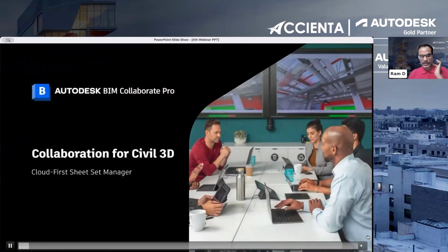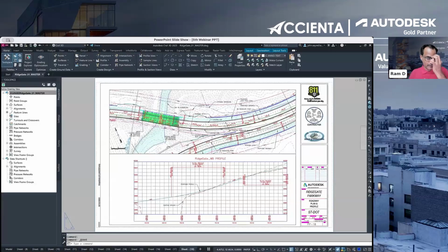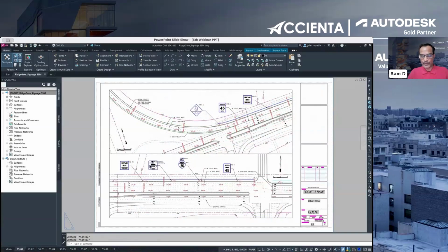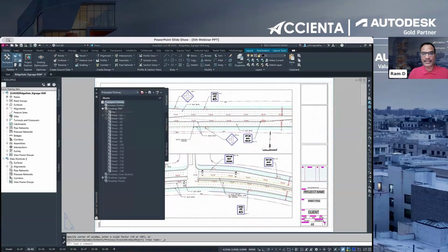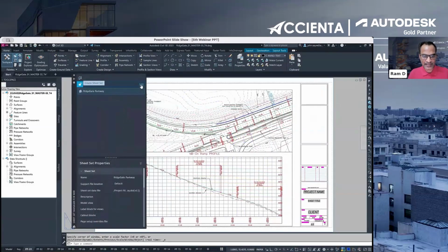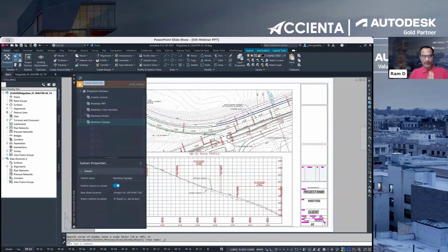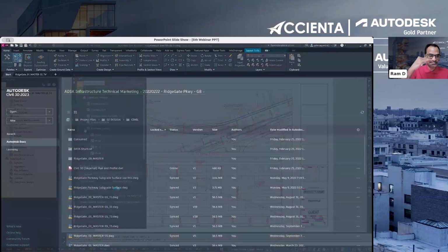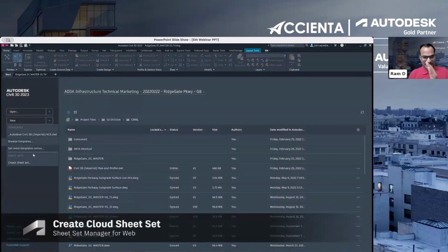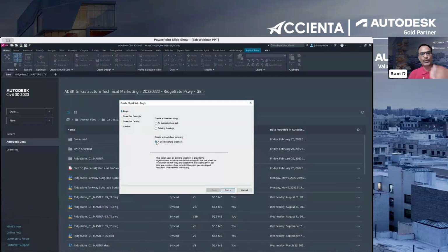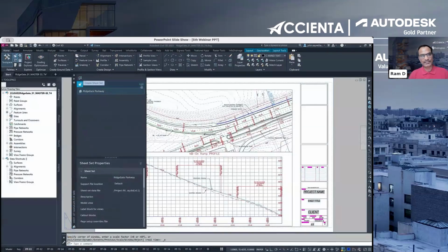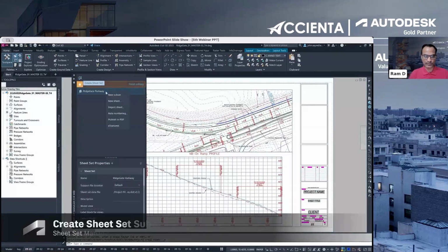Great. So now, the product you are using here for your civil infrastructure and the complex project is Civil 3D. This is the software. It looks amazing. If you are a very experienced AutoCAD person, you can easily see the interface looks like AutoCAD itself. And now we have just kept the sheet set manager open. What happened here is, in one drawing, the set of sheets that you have created, we're going to summarize and then add it as a sheet set manager, like kind of a workflow. Once the sheet set manager is assigned, we're going to create a sheet set here to pull the layout and see the list of sheet sets with the sheets aligned accordingly. So that's what we're going to do here.